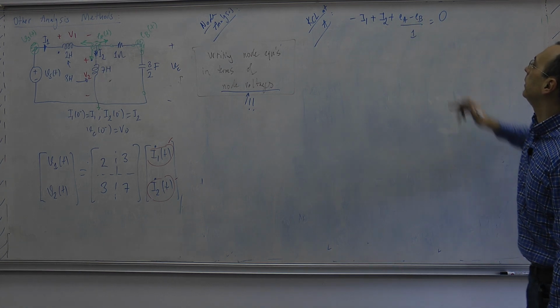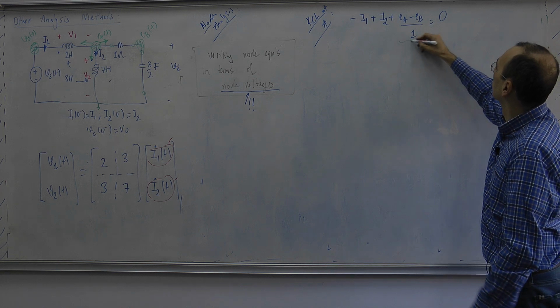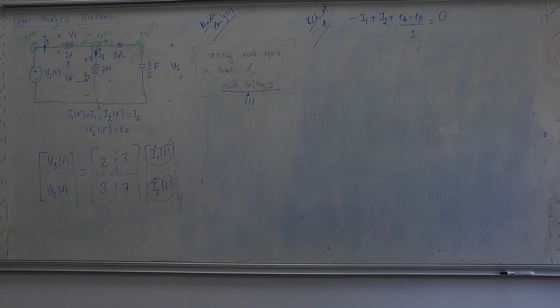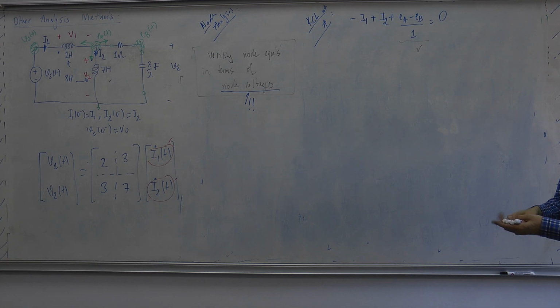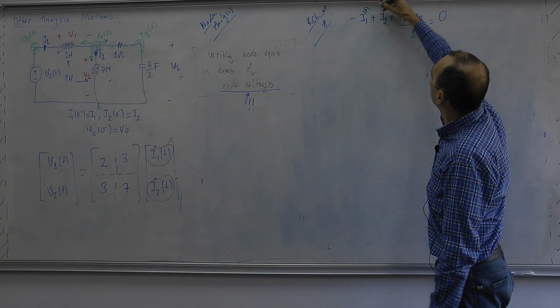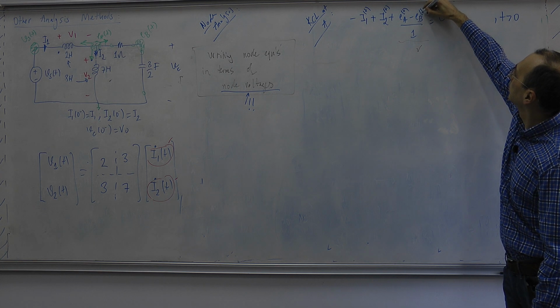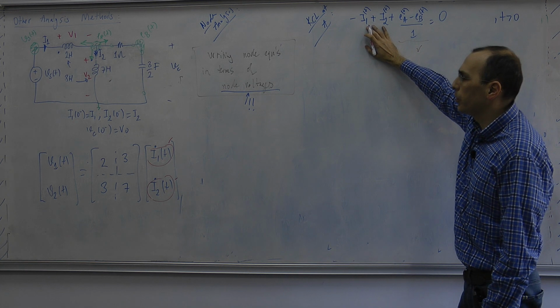This EA minus EB, again, I'm very happy with this term because I see node voltages present over here. I'm not happy with the I1, I2 terms because these are some other unknowns of this problem. They are inductor current number 1 and inductor current number 2. And this is my KCL, which is supposed to be satisfied, left-hand side, right-hand side, for all t. These are all t-dependent, unknown functions. So how can I express I1 and I2?